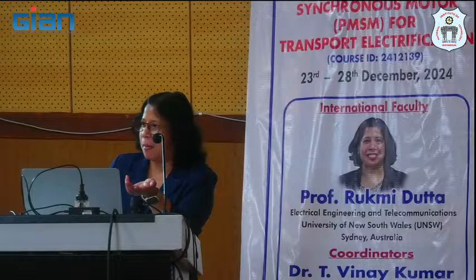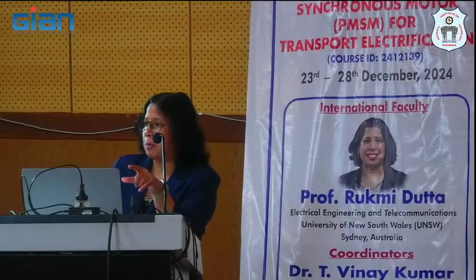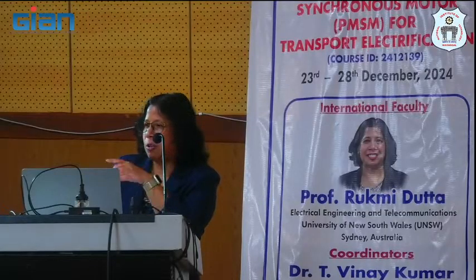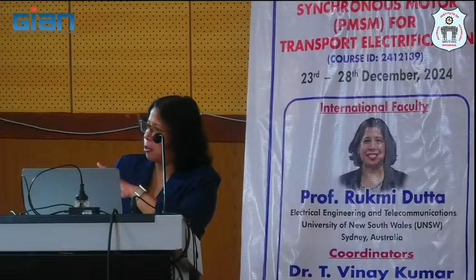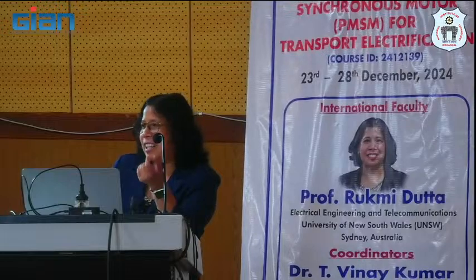It's not a general comment. Maybe specific to your setup it was doing that. But more, the problem is that it may not be able to produce the torque that it can actually produce, right? If we do V/F. Like for an experiment, in our undergraduate courses also they do some experiment of V/F control of the PMSM just to understand. So it works, yeah, it does work, but you don't get the best performance out of it.